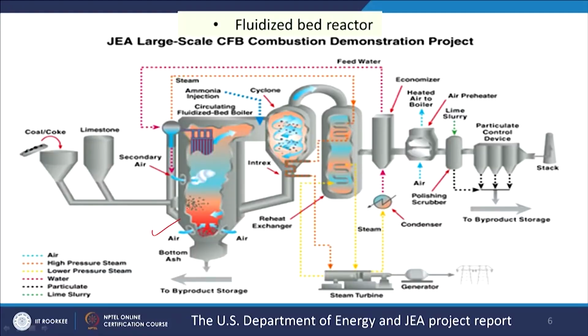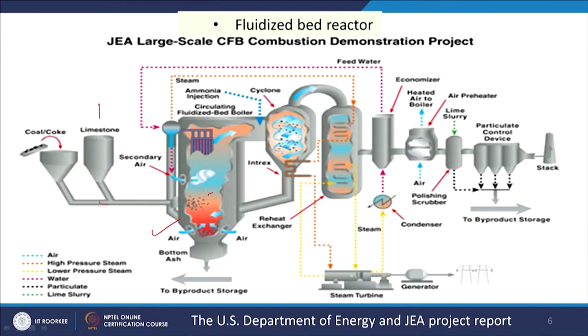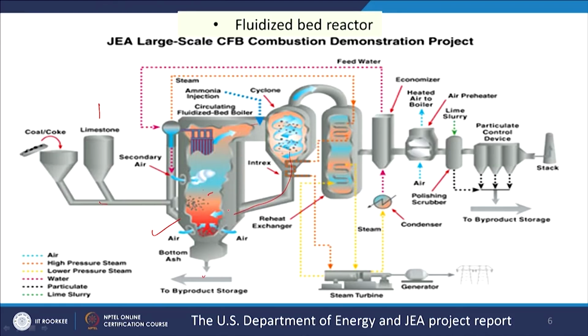Apart from this, the fluidized bed reactor can also give us some other advantages. Say we can add limestone here with the feedstock. So, feedstock and limestone are coming here. All our solid particles are fluidized and then in situ SOx capture is possible. The limestone will react with the SO2 and it will settle here. That is one additional advantage, and if the fine particles come here, they also get some recycling possibilities. So, we get more conversion of the carbon in this fluidized bed reactor.